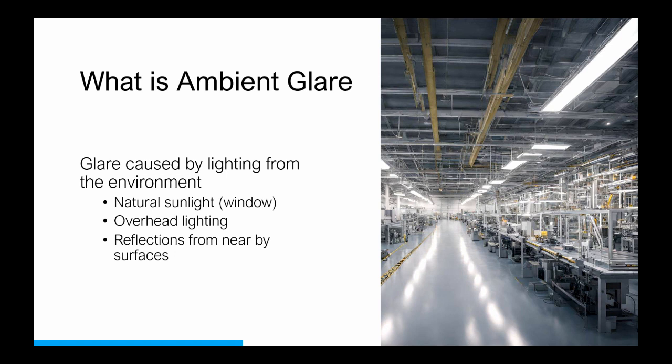We've had some applications, and by some I mean one, where the light was illuminating down, that our machine vision light, and it created a good image. When we had it set up in the lab, there was no glare. We recommended the light. The customer installed the light in their machine, and they were getting a lot of glare that was causing problems that they couldn't get around.